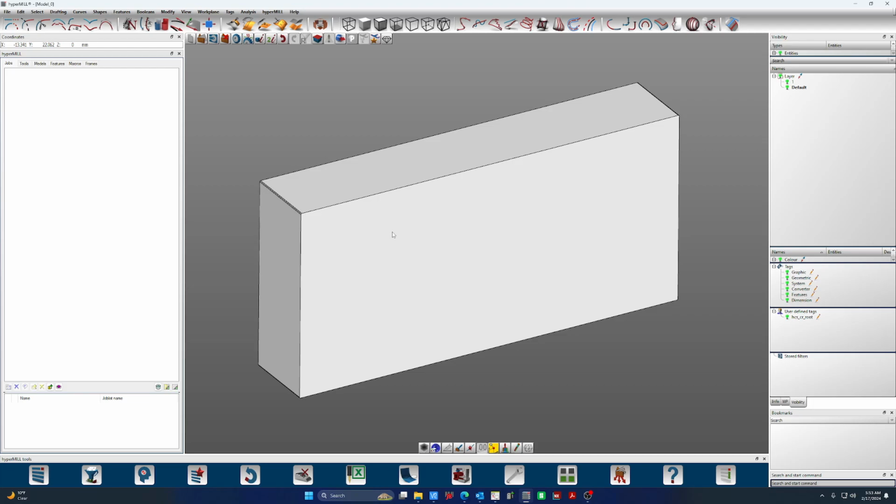Now, there's some best practices there. The gist of it is, if we take the time to make all our own geometry on here and drive toolpaths from that geometry, we can take this model, punch holes in it, make it bigger, so we can do all of these things. And at least for the toolpaths that are driven off certain pieces of recreated geometry, those will sort of stay together versus things that are driven off your 3D model that are modified. As soon as you modify the model, you're going to break them.